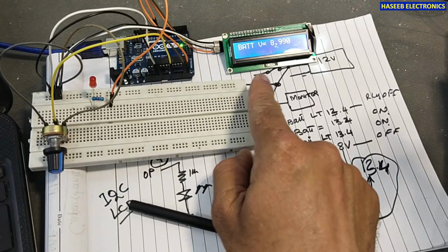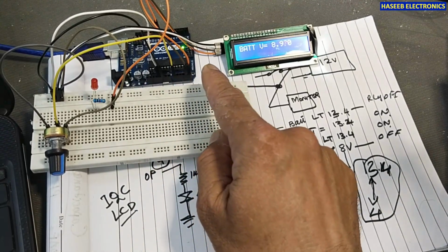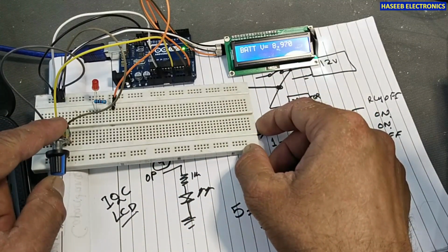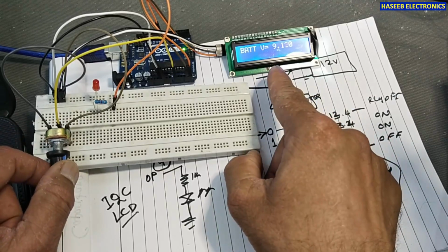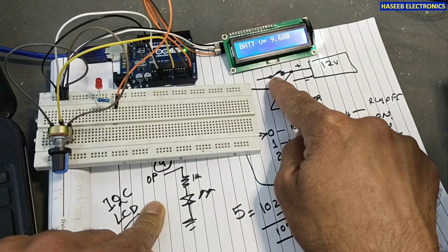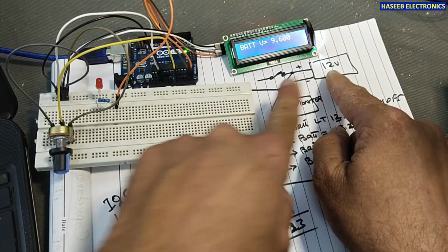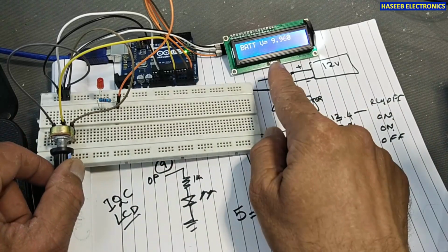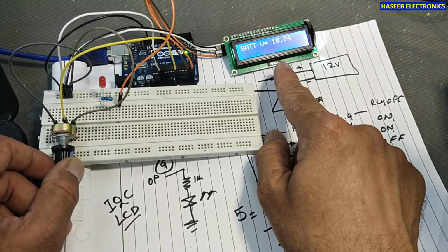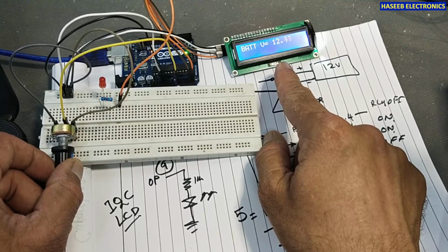In this session, I created a project. This is a battery monitoring circuit and it will control the charging and discharging level of the battery. For example, this is a battery simulator. When the battery is reaching 13.4 volt, this time the battery is charging. This relay is off. When the relay is off, the points are closed, the charger is connected to the battery and the relay is off. When we reach 13.4 volt, you can assign your own value at which level you want to disconnect it. At 13.4 volt,